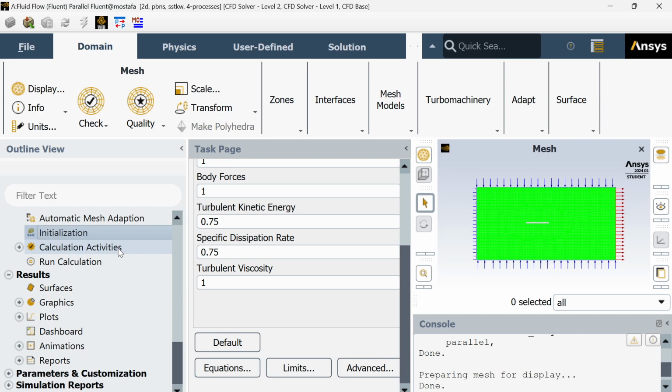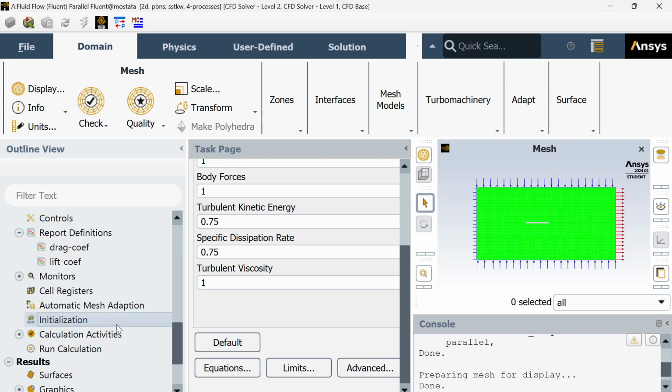Essentially, the difference between the initial guess and the final solution is called the residual, and it is representative of your error. Then we use that final solution as an initial guess for the next step, and it will go on and on until the difference between the initial guess and the solution becomes very small, smaller than your desired error value, and that's when you have converged to a solution.